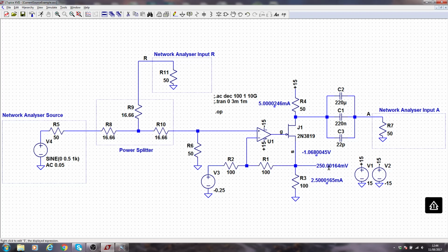If I ask for copy this one, what node is this? That's node S. Oh yeah, because I labelled it. If you need to label your nodes, by the way, F4. I could, if I wanted to, put an input node just here. If you label up your nodes, you can then demand V open brackets input close brackets. If you do that though, you must rerun the simulation.